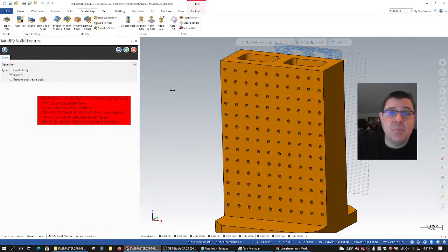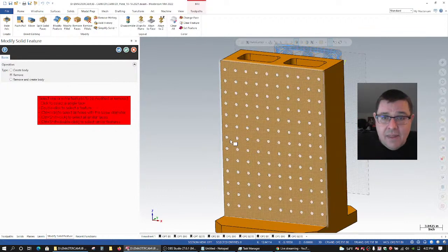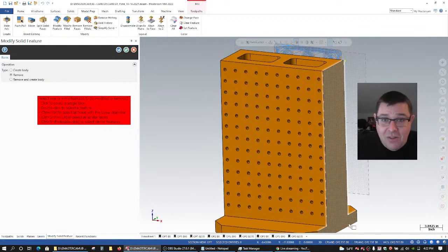Make and save a copy on a different level. Remove history on the copy. Make it a new color, right? Make it different from the original in some way. Save your part file, and then do your modification work on the copied solid that is now a different color and a completely new solid because you've stripped away the history.